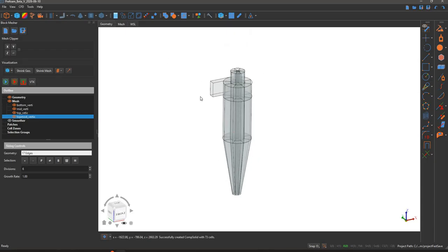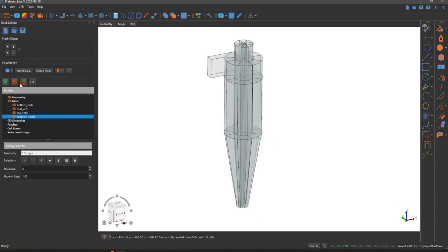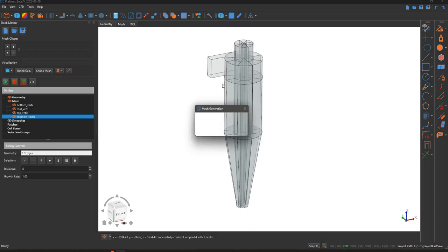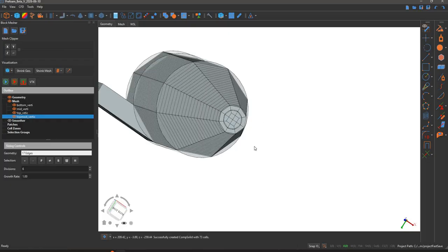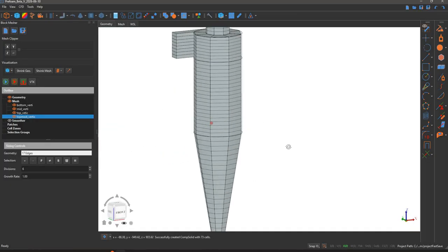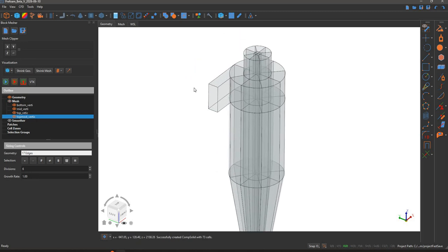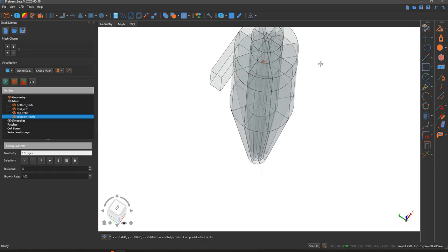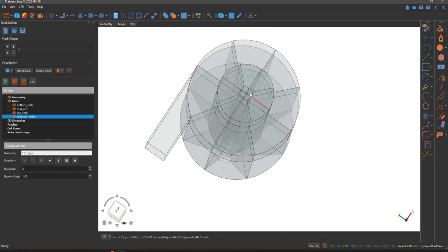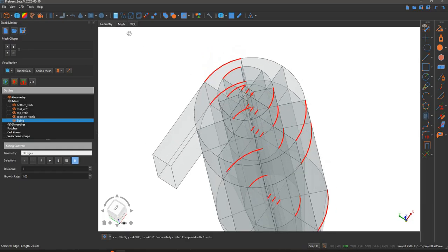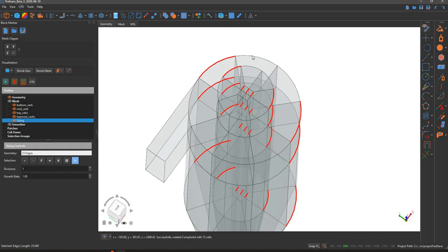If you want to look at what the mesh until now will look like, you can hit this red button and you will get the mesh up until now. We basically only changed a couple of the settings here, so you won't see much. After this, what's remaining are the radial sizing, I guess. So if I hit this, propagate and then highlight, you will see there are still some edges missing.